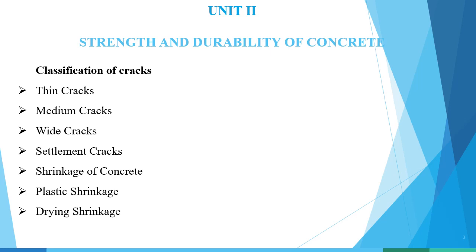But at a given workability, which approximately means a constant water content, shrinkage is unaffected by increases in cement content, or shrinkage even decreases because of lower water cement ratio. At lower water cement ratio, concrete is stronger to resist shrinkage, but it should not be forgotten that stronger concrete creeps less, has less stress relaxation and therefore more microcracks.